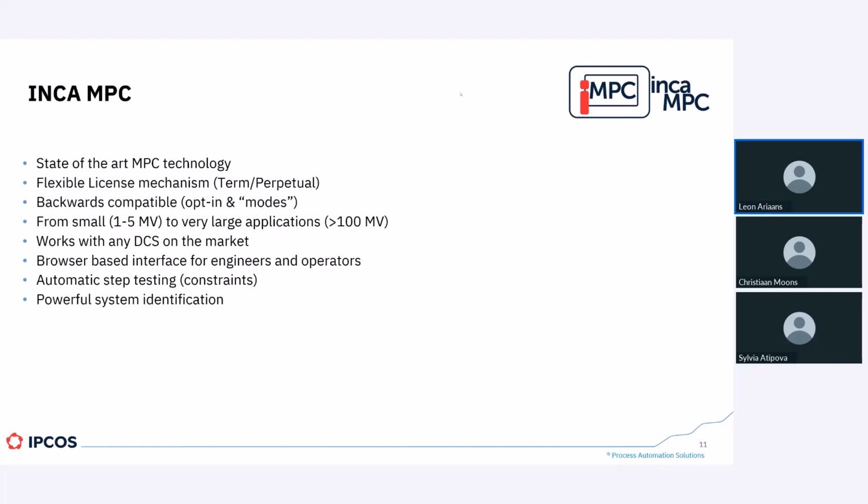And going beyond that, INCA Discovery was actually the first in the industry that allowed you to specify that there are certain mass balance constraints or gain ratio constraints that should be present between certain curves. If you have that knowledge, you can impose them on the system identification, and the system identification will reflect that information during the identification already. It's not a post-processing that you do.